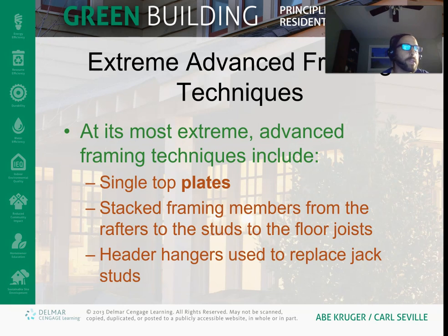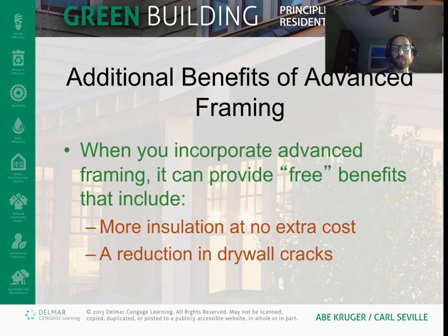But ultimately, the building, if you live in it long enough, will pay for itself by reducing your energy costs. So these are just some examples of the advanced framing techniques we'll get into a little bit. You basically just want to reduce the amount of wood as much as possible. Again, that's the big thing here, extra insulation.